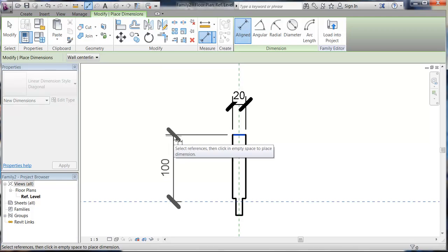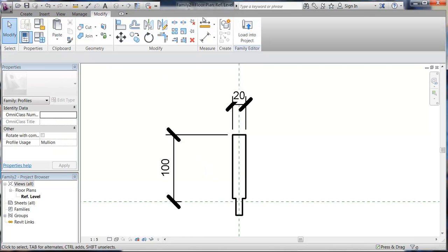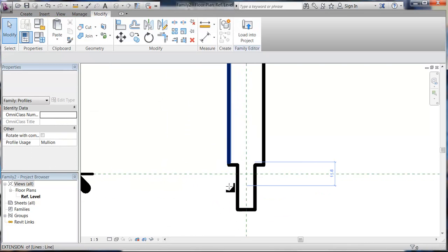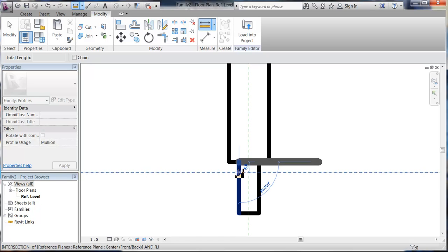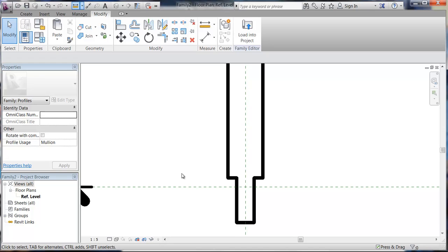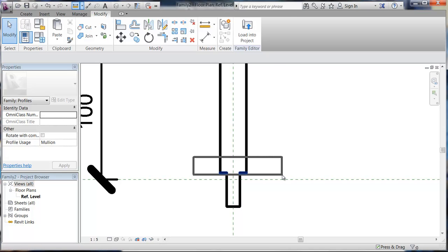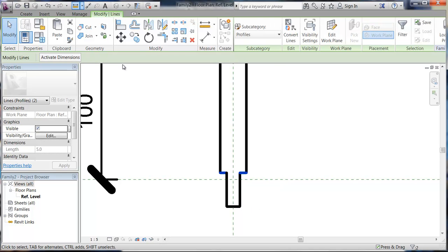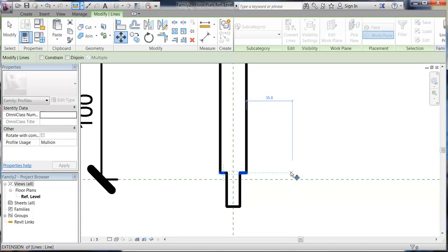So the overall set out there from the glass is 100 actually, but let me just think for 1 second. It's 25 mil at the moment. I'll probably change it to 20, but yeah, we've only got 5 there, so I wasn't thinking. So that's 5 mil too low. So I'm going to just select it with the window, and again, you can use move. Your base point, just move that 5 mil.